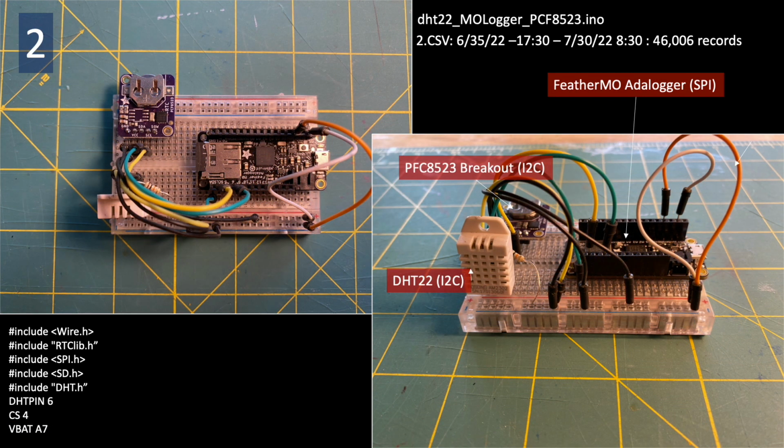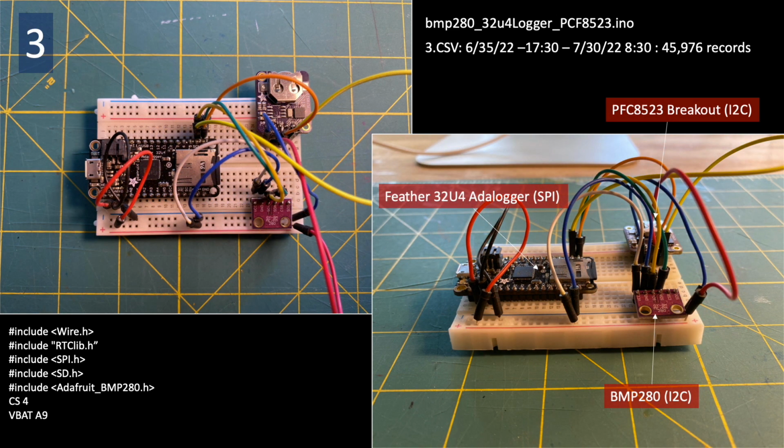And here's the setup for a Feather M0 datalogger that's driving a DHT22, as well as a PCF8523 real-time clock, which communicates over I2C. And here's the setup for a Feather 32U4 datalogger talking to a BMP280 as well as a PCF8523 RTC.